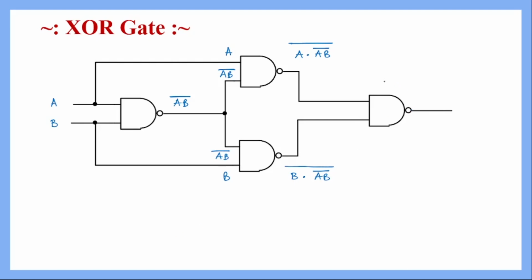So what we are doing here, we are performing a NAND operation again. In this case, our inputs are A and (AB complement), with the whole complement, as one input, and then the second input. First we are performing the AND operation and then the NOT operation. To simplify this expression, we will use De Morgan's laws. So what we can see here is (AB) bar.